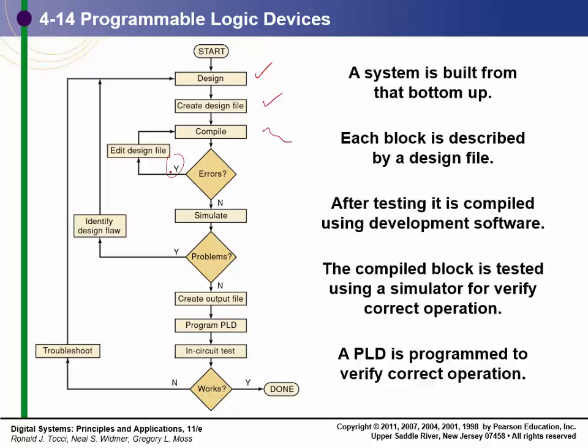I had one pin that is not connected. I go back there. I simulate it. If it simulates right, great. If the simulation's wrong, I go back and I modify my design. I create the output file, I program the PLD, and then I test it. And as you recall, I did a very simple 4 input and/or circuit, and I went to the point where I was flipping the switches to verify that it worked. So this is a typical design process, and inshallah, you'll be going through this process with some projects here.